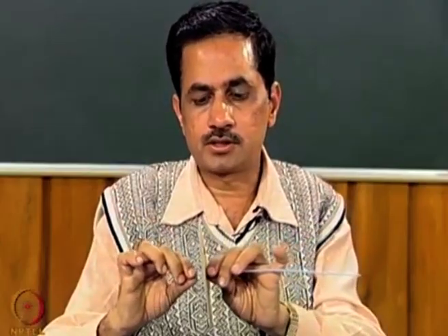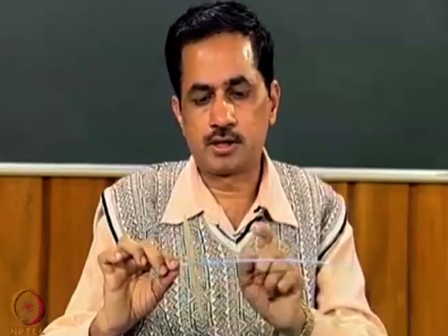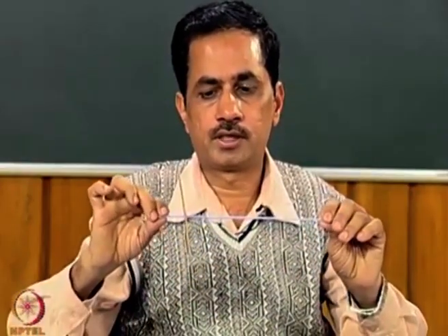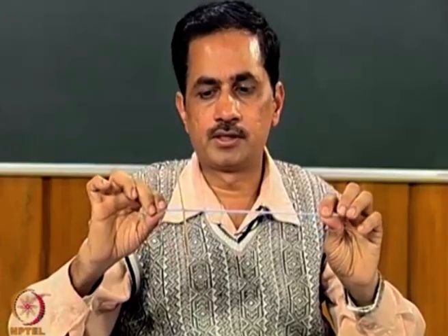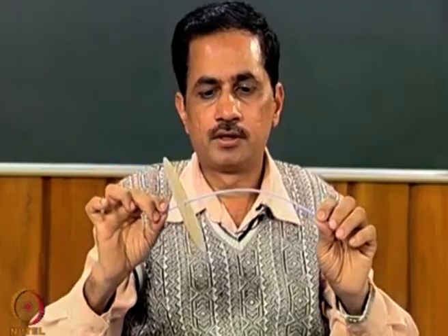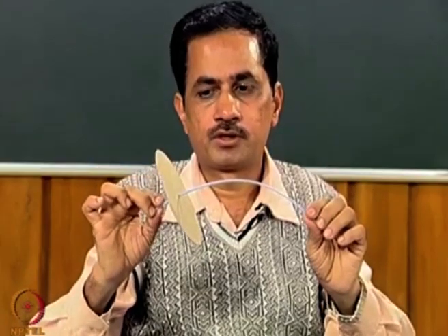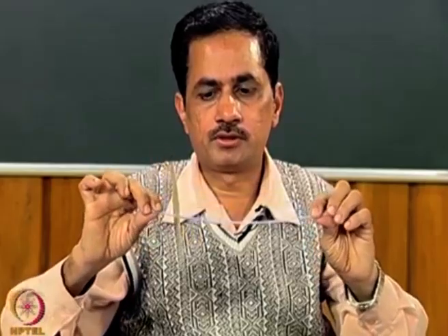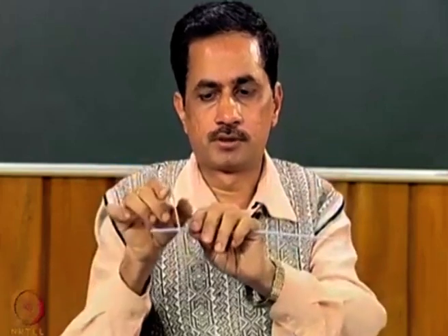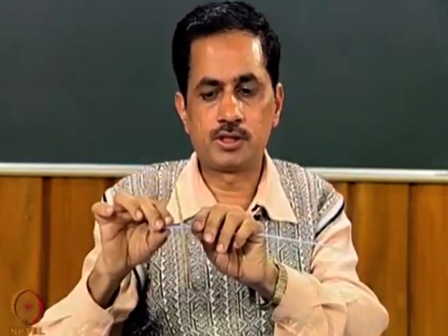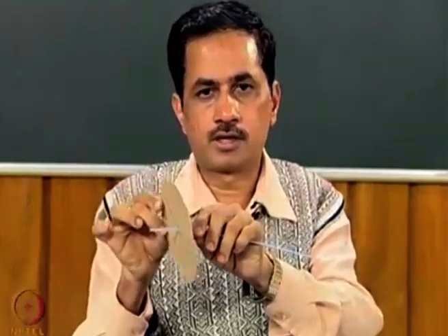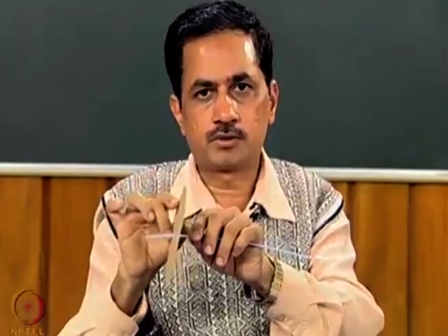But if the same disc is at an offset, not at the center, now you will see that at equilibrium the disc will be vertical, but when the shaft is wobbling, the disc tilts. You can see that during whirling it tilts about its diameter, and this particular motion is taking place in two planes. So continuous wobbling of this disc will take place.